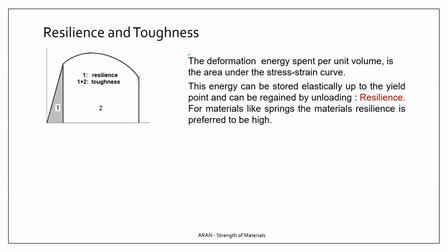It can be shown that the deformation energy spent per unit volume is the area under the stress-strain curve. For example, if you take a specimen and you load it, you spend energy up to the yield point, you will see this dark area, area number 1. This is the energy which can be stored elastically. So when you release the load, this energy can be regained.